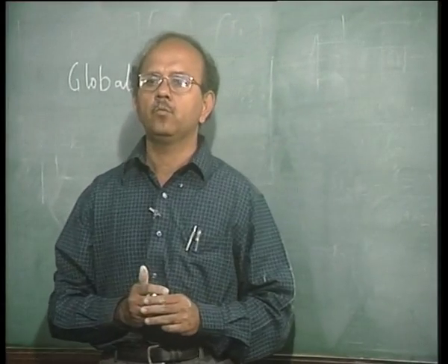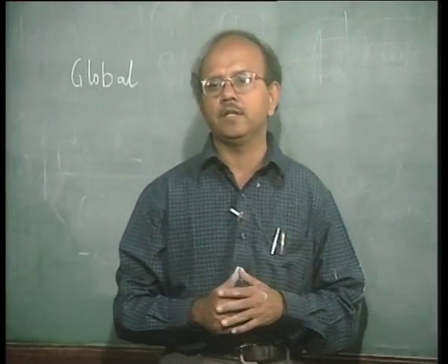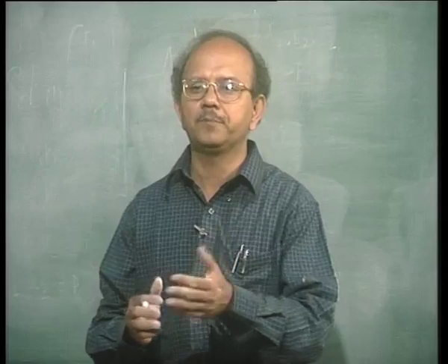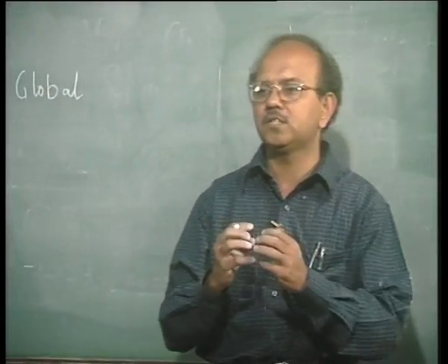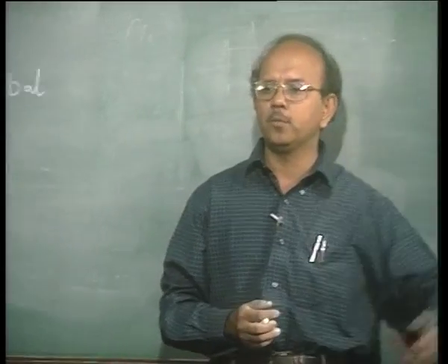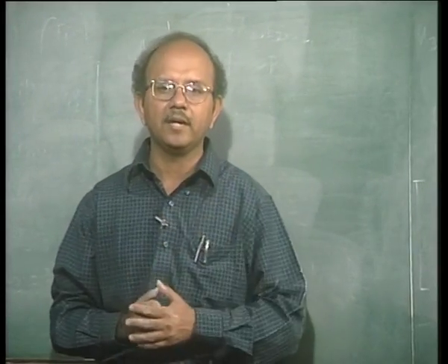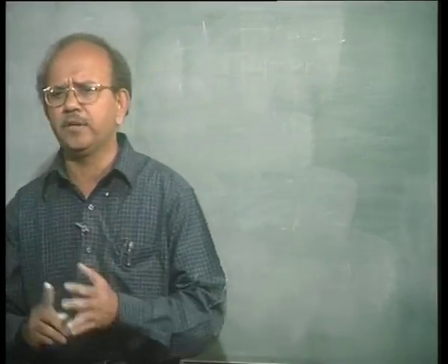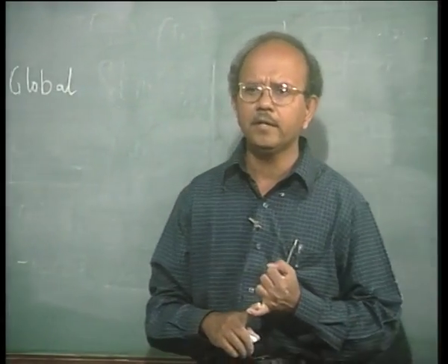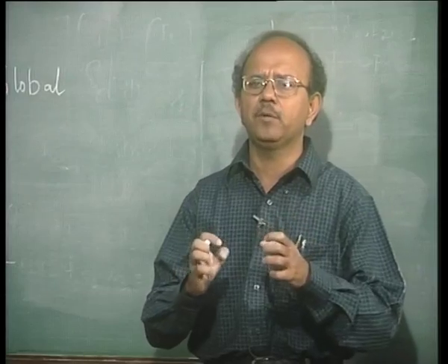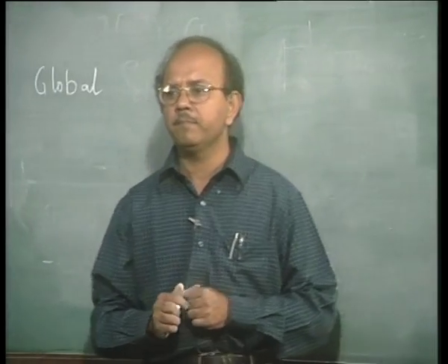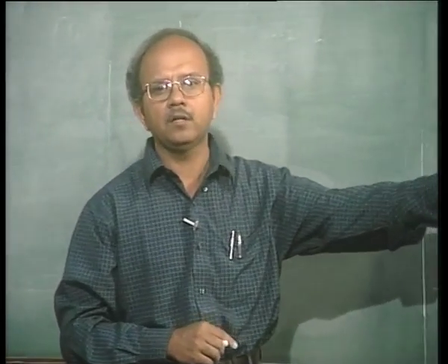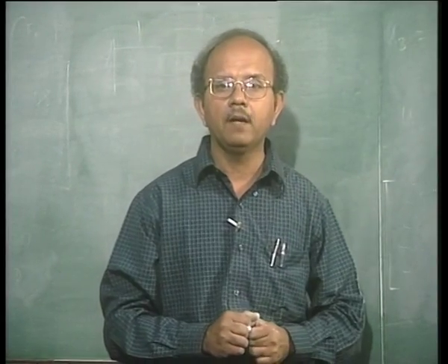What is it that we are going to change, or why we should change our thinking? Now, in the uniaxial problem, we did not have much difficulty in understanding stress, because stress, we said, is just E into epsilon, finished. There is only one stress called sigma, and it turns out to be the same as load per unit area, P by A1, P by A2, and so on. So there are two very simple definitions we used. One is to define strain, just change in length by original length. The other one which we used was just E into epsilon, which turns out to be P by A.